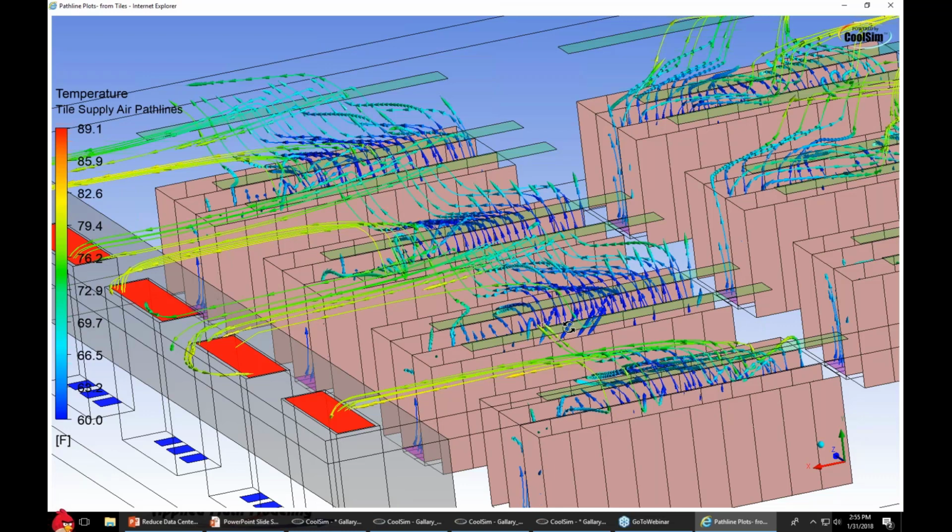And yes, you do need to be sensitive to high temperature on the return path, going by things that might be sensitive to that temperature. Of course, the chiller loves it. The chiller wants it as hot as it can get it because it has to do less work, and the efficiency of your data center will improve dramatically, as well as the window of economizer operation if you're using one.